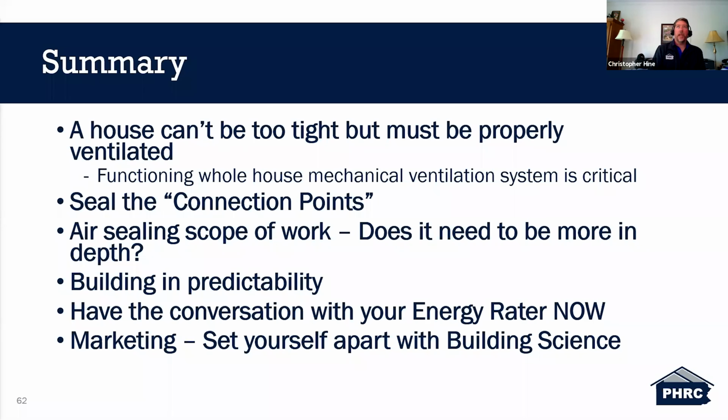And that exhaust only, you want to make sure that it's critical that it's working correctly. So take a look at your whole house mechanical ventilation systems. Seal those connection points, whether it's the wood framing to the foundation, or the subfloor to the wall, or the wall to the ceiling. It's those connection points that, if they're going to leak, they're going to leak the most. So pay attention to those, make sure they're sealed up, and that'll get you on your way to the 3 ACH50.